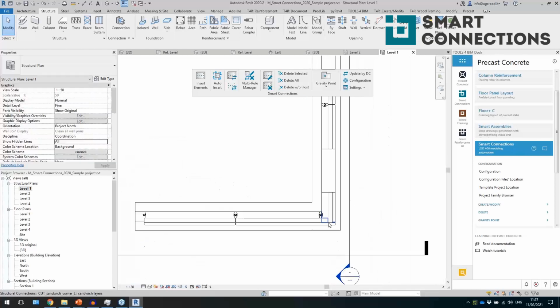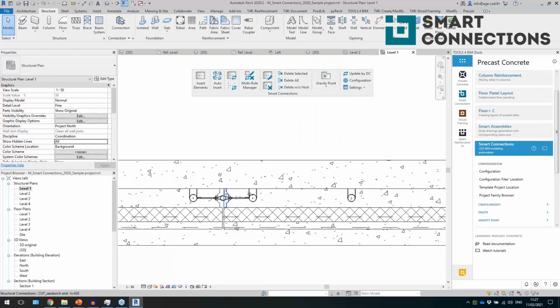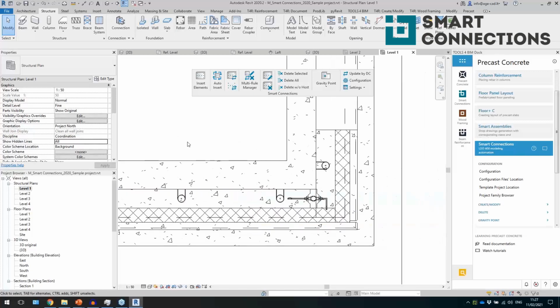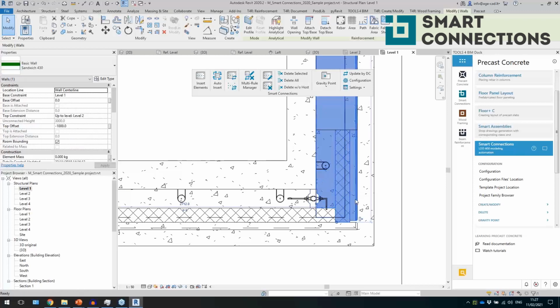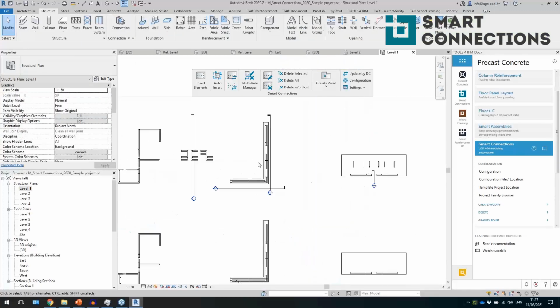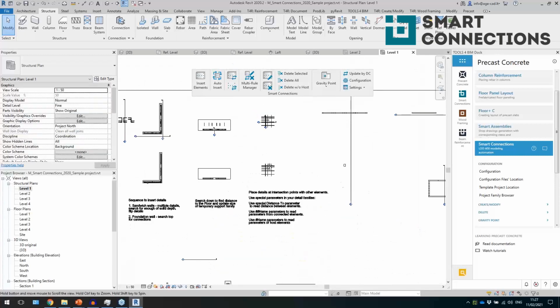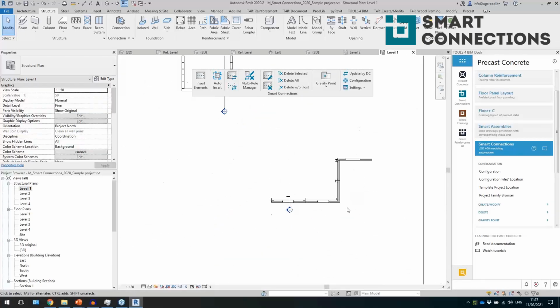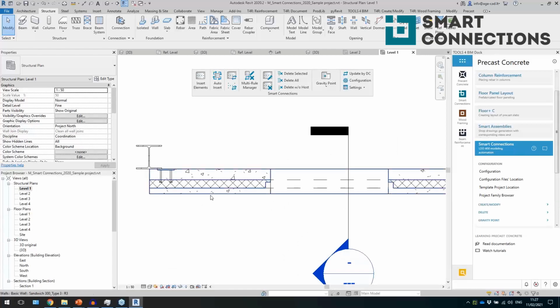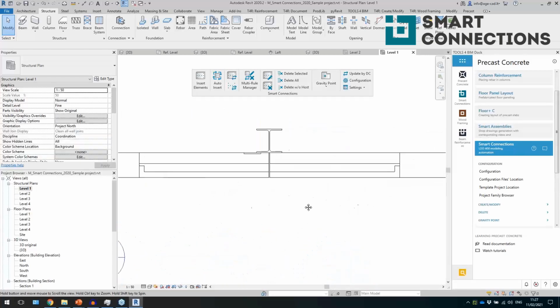Then I have sandwich walls, where I was using this kind of cut families to get the shape of my joint, and then shape in the corner the same way. So I get this kind of shape for the sandwich wall connection. Then I have here another example with walls over here. So I have a wall with some windows, right?